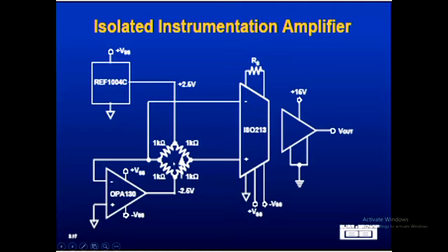0 volts in the middle, but don't forget this resistor can change things, so that point can be somewhere between minus 2.5 volts and plus 2.5 volts, depending on how extreme the value ends up being here for that resistance. So in response to some stimulus, this resistance can change, pushing this voltage up or pulling it down. Good.